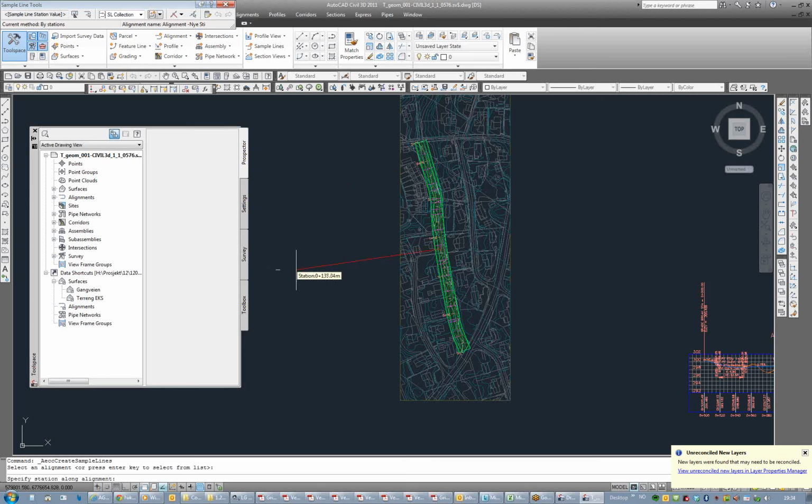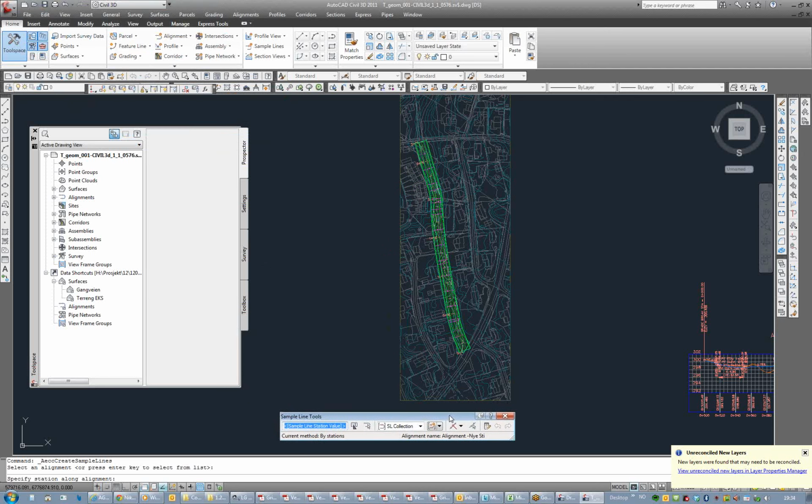Look at your toolbar up there in the top left corner. Right now it's giving you a chance to just pick one spot. But if you click on the down arrow next to where that little red line is, that one, click on that, by range of stations.